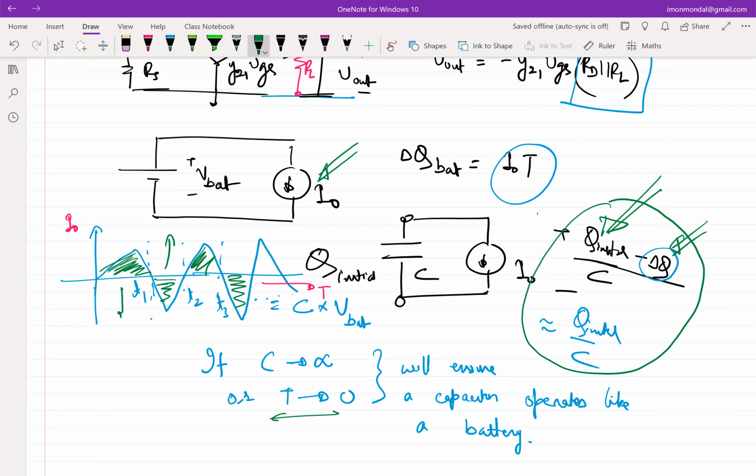Yes. So in the problems that we used to do earlier, the current we applied had a zero mean signal. Yes, so the problems are implicitly set like that. Right? What I'm trying to say is that sometimes we make the statement that an infinite capacitor acts as a short circuit, and that is because the underlying assumption is that the signal it is trying to process is not zero mean. So if the signal has a DC component, regardless of how large the capacitor is, the signal will not flow through. Zero mean means zero DC. What is the mean of a signal? The mean of a signal is the DC part of the signal. The current cannot have a DC part. That's all it means.